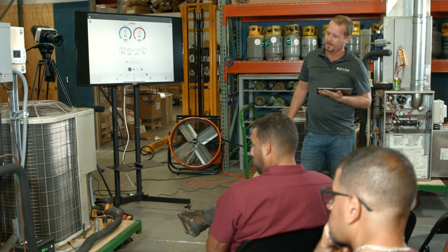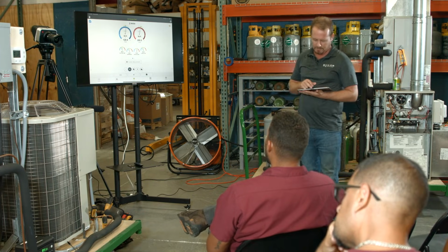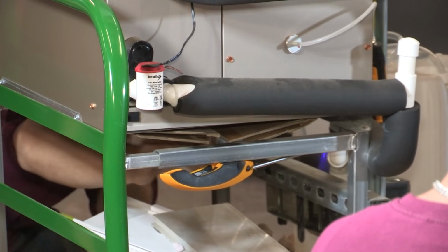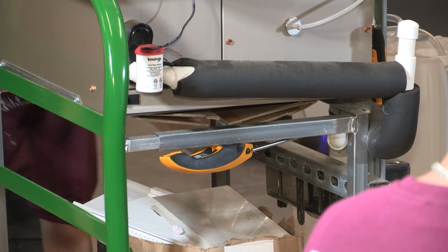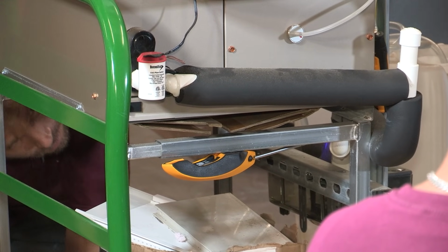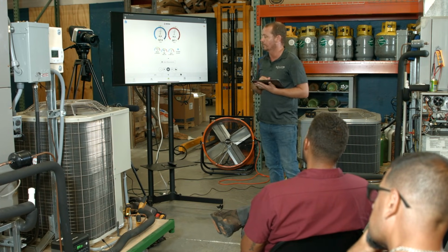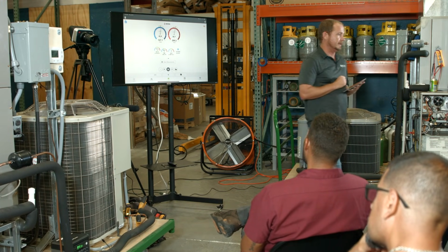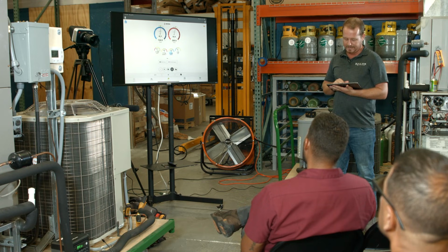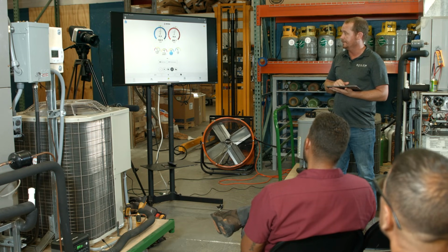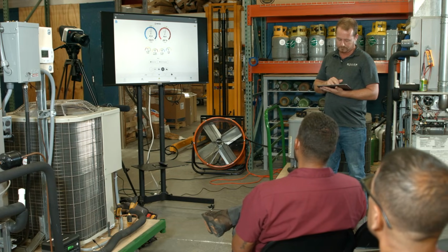All right, now Bert is severely plugging the return. You're going to notice our air temperature split will probably start increasing as well, as we move air more slowly over that evaporator coil. It's going to give up more heat. Our latent capacity is going sky high because we're moving less air. What about the pressure ratio? Look at our total capacity.